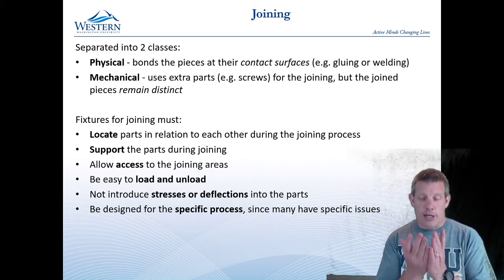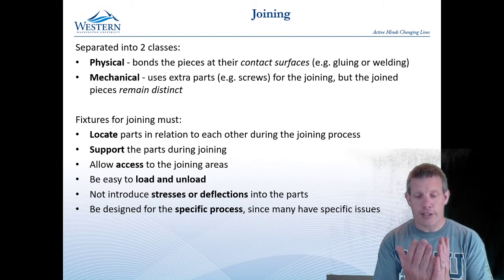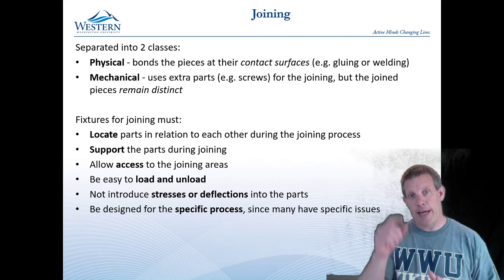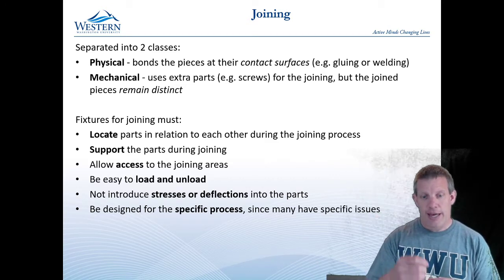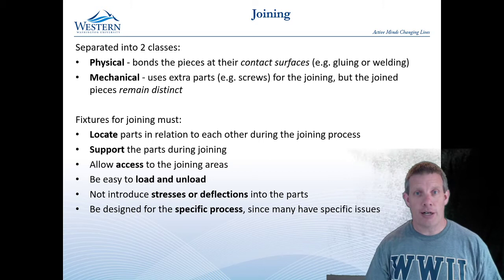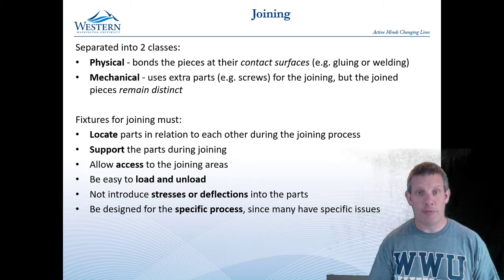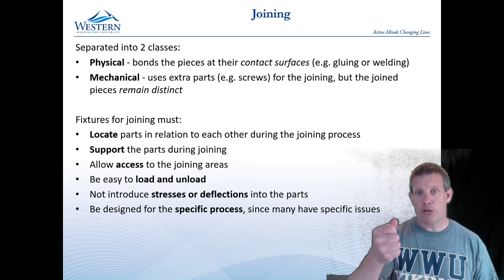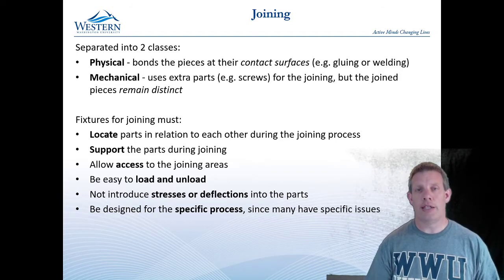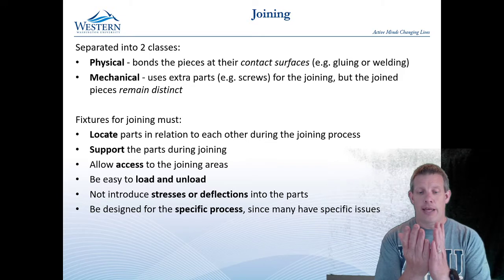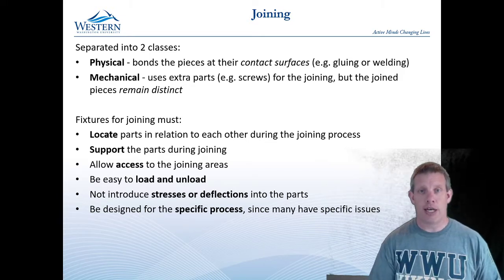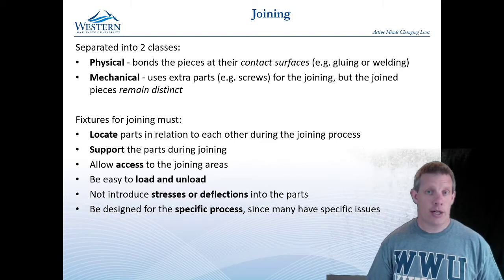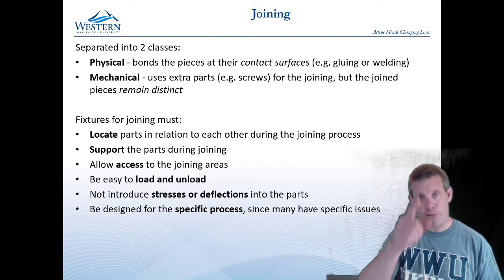This is readily apparent in welding fixtures where there's a bunch of thermal expansion that takes place. As you run that weld bead, that edge of the part or whatever you're welding will be getting considerably longer. If you have it clamped so hard in the fixture that is being created, then they will warp out to the side if they're being held tightly enough, and that will cause the part to end up with a warped shape.